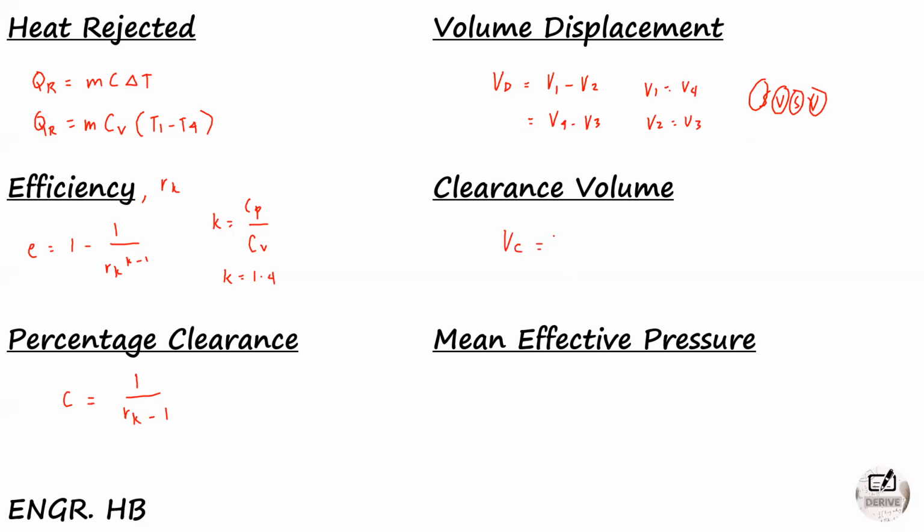Of course, if we have a percentage clearance and volume displacement, meron din tayong clearance volume that is represented by VC, and that is equal to the percentage clearance multiplied by the volume displacement. Of course, clearance volume is in cubic meter then, or cubic feet, or whatsoever volumetric unit.